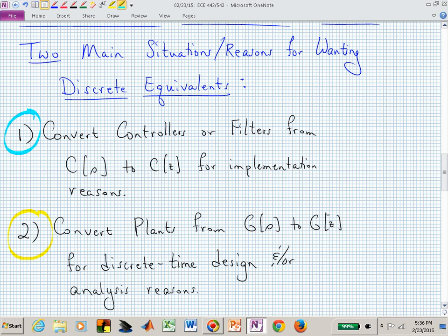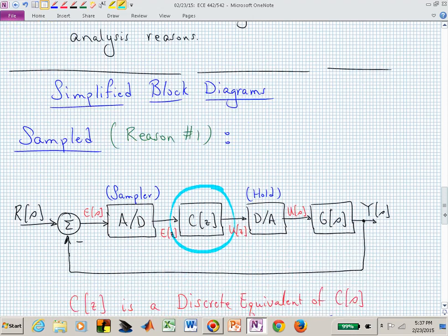A zero order hold means we have no more information other than the constant value that we're looking at right now, and we're holding that flat. There's no slope to it, which might constitute a first order hold. We just want a zero order hold, which says hold a value constant during the sample time period, and that will become clear in just a minute.